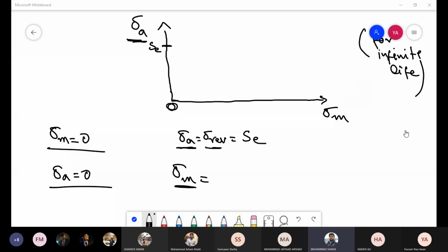Yielding point. It could be yielding, but in this case, because we are comparing it with fatigue, and fatigue is a fracture phenomenon, generally we don't talk about yielding related to fatigue, we talk about SUT. So we use SUT as our limit.